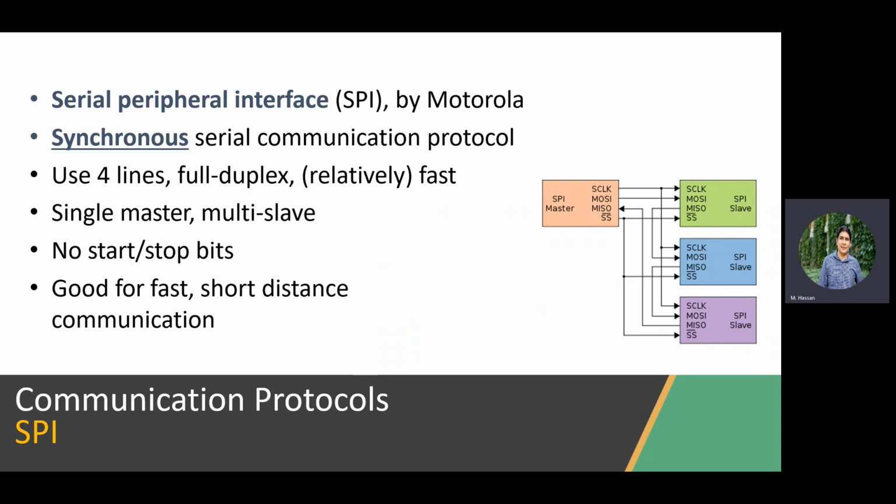And because you have sender and receiver, it uses what we call 4 lines. Well, I won't go through the actual bits because you will do this already when you go through the data sheet of lab one. But because it's synchronous, you don't need stop bits. Its limitation is you can have a single master, multiple slaves, which means you can target multiple destinations at the same time, and it's very good for speed. Right? Doesn't mean that SPI is always winning over I2C, right?